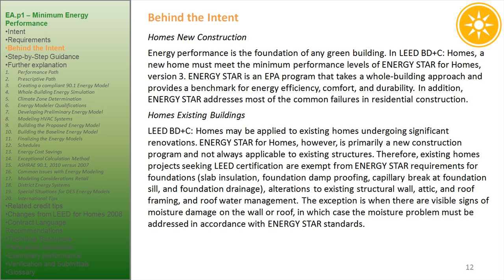Therefore, existing homes projects seeking LEED certification are exempt from Energy Star requirements for foundations, slab insulation, foundation damp proofing, capillary break at foundation sill, and foundation drainage, alterations to existing structural wall, attic, and roof framing, and roof water management. The exception is when there are visible signs of moisture damage on the wall or roof, in which case the moisture problem must be addressed in accordance with Energy Star standards.